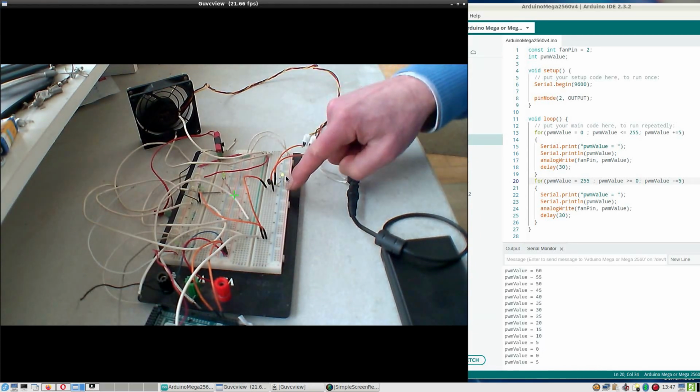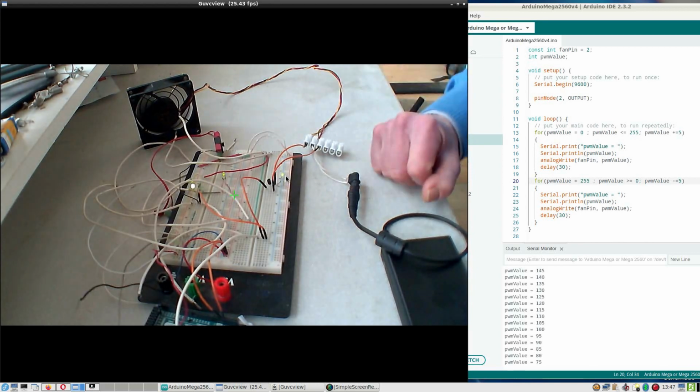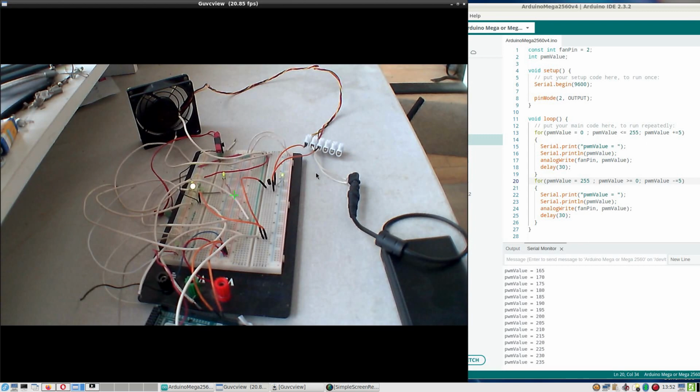So I have to see if there is a problem with the transistor or in another way, because this is clearly not working. Another problem is that although this works given the output, an example I found on the same subject, which is controlling a DC fan of 12 volts, uses digital write and not a pulse width modulation value, but just high and low, or on and off.